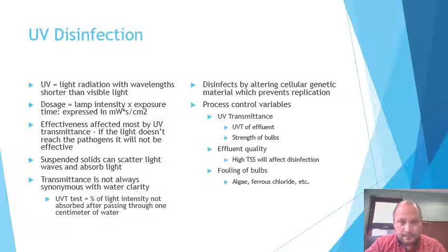As with chlorine, we're looking at a dosage required to provide adequate disinfection. With ultraviolet disinfection, the dosage is a function of lamp intensity, or how bright the lamps are burning, times exposure, or how long the contact time is that your effluent is flowing past the UV bulbs. At least with our system, there's an algorithm that calculates the dosage based on that.